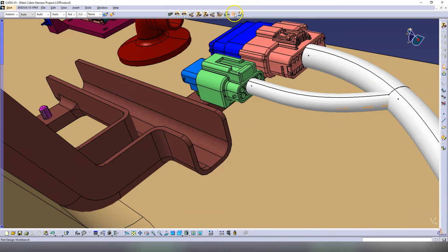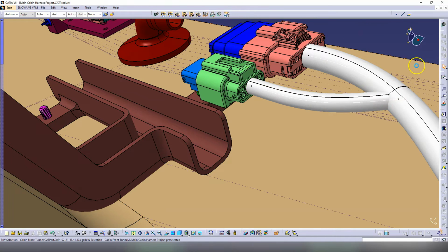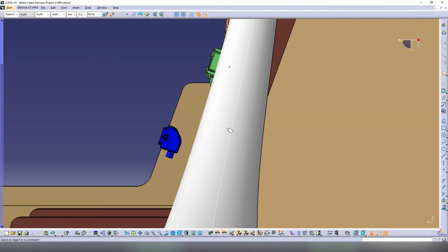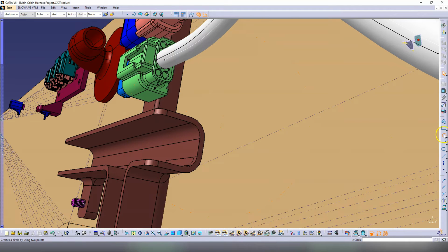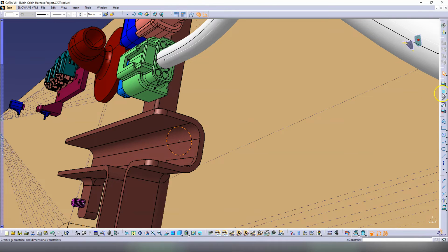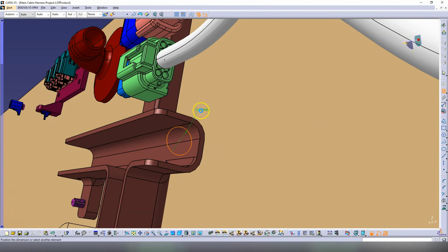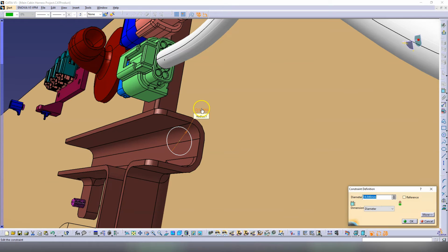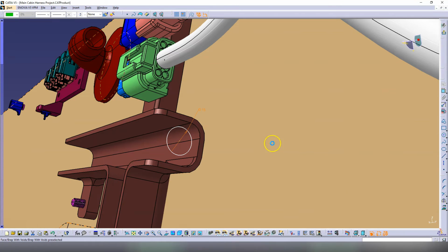So this is how I usually go into part design. I put a sketch. The sketch is inside the file of the branchable, because that's a cut part file. You can add anything from the part design workbench in it. So I'm just going to add a sketch on this surface. The sketch is right here, and I'm going to add a circle on that sketch, which is going to have the diameter of the bundle, in this case 15.